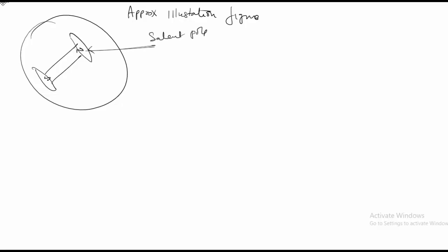You can see there is my direct axis, which is this, and my quadrature axis at 90 degrees. So this is my Xq and this is my Xd reactance. Based on this and the circuit model, it is possible to draw the phasor diagram.